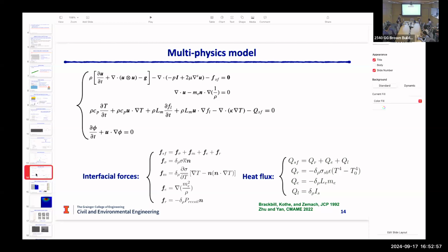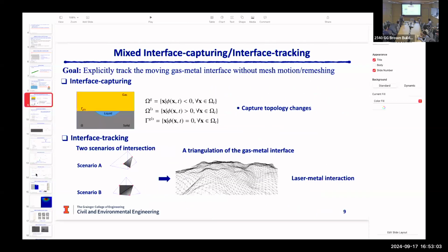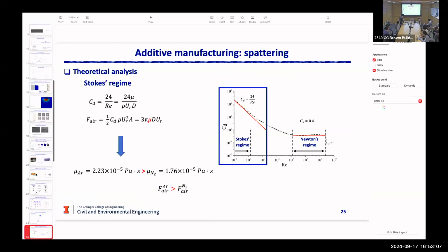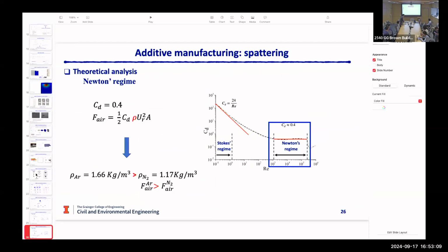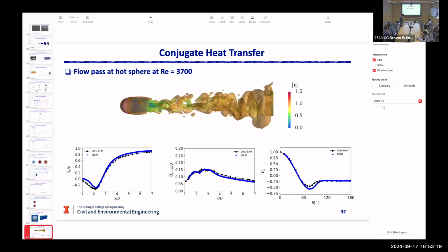I think when I mentioned stabilization, it is mainly for the turbulent flow, because you truly don't want to go with direct numerical simulation. I think you're kind of a fluid mechanics person, so you know direct numerical simulation needs a really fine mesh. So the stabilized method is more like a model that allows you to obtain reasonably accurate results using a relatively coarse mesh.